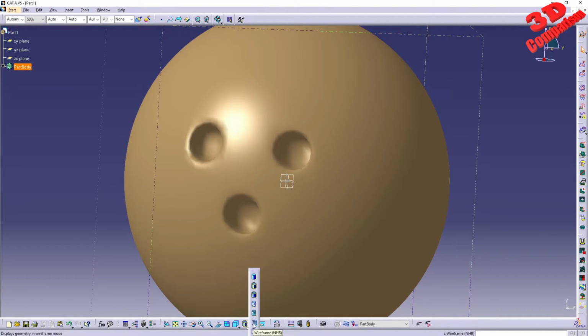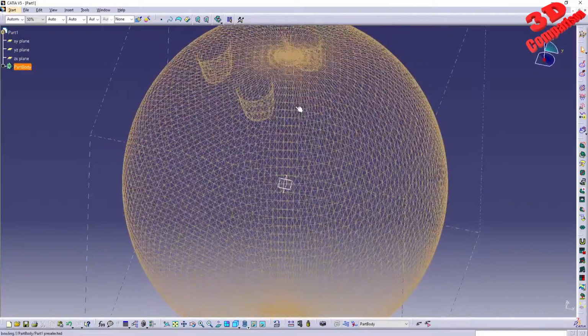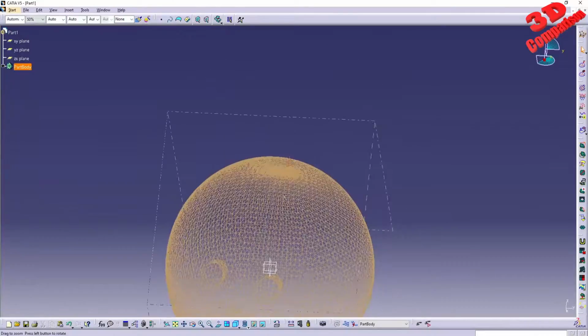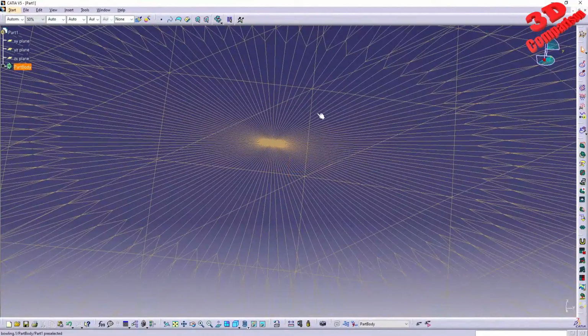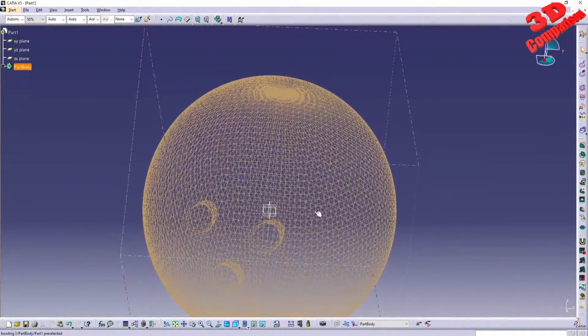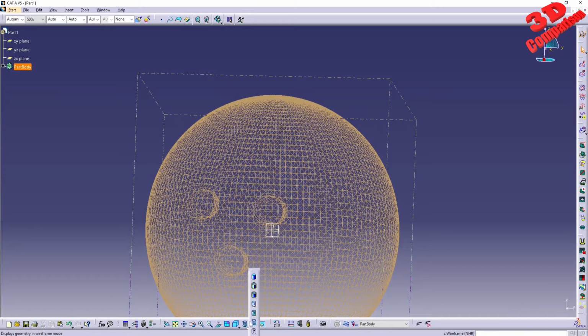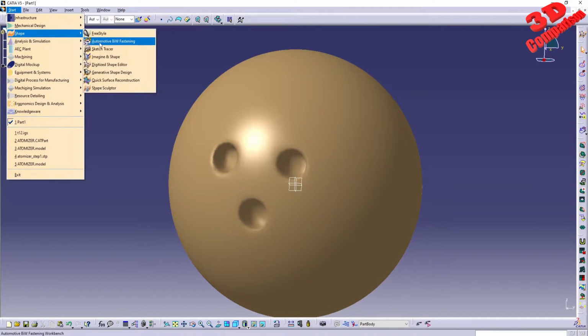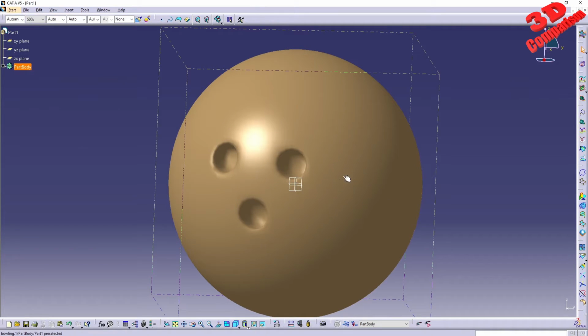If I'm gonna take a look at the wireframe, we're gonna see that the wireframe of this will be the same as the one within Blender or Fusion, and we still have this vertex over here, which is connected to a lot of elements. But now we have the possibility to use the other shape features within Quick Surface Reconstruction to have this converted.